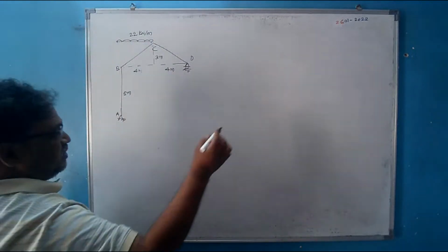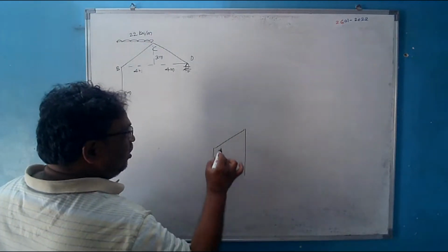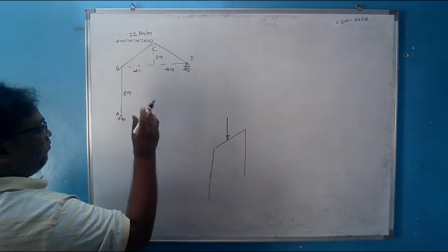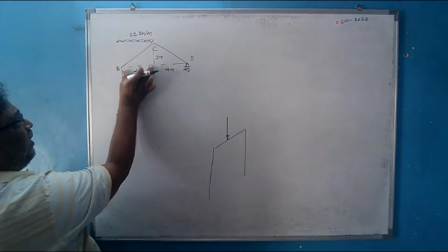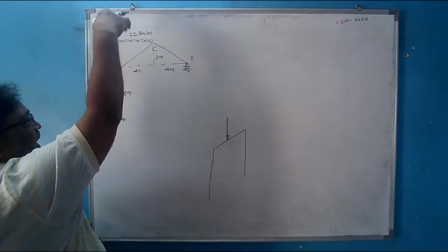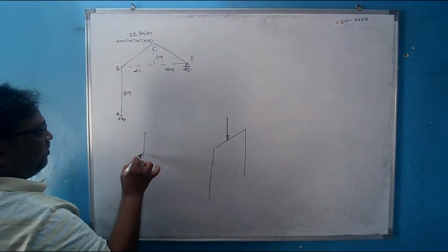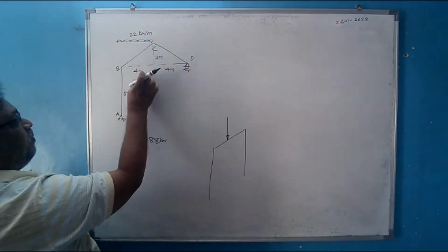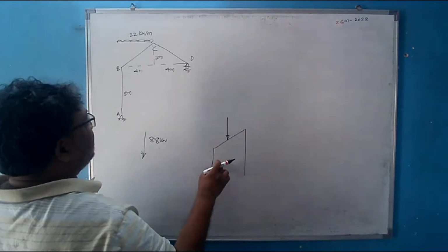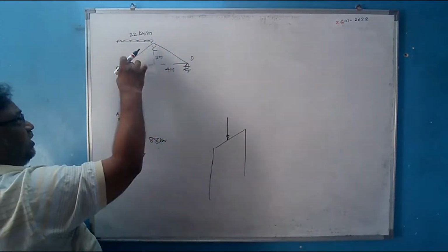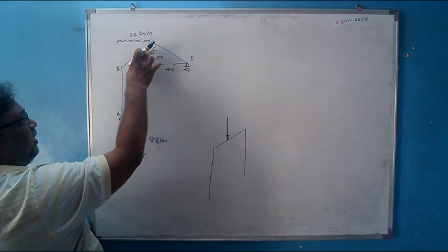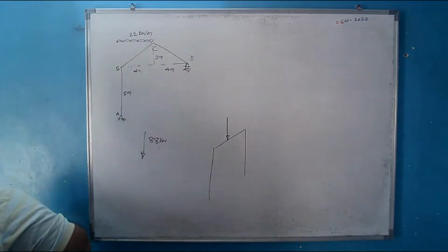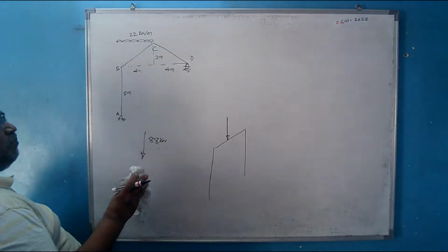It is acting vertical. जैसे हमारा जो पिछला प्रॉब्लम था जो हमने सॉल्व किया, तो उसमें भी यहाँ पर एक फोर्स ऐसे एक्ट हो रहा था. This was acting perpendicular to this member. So here also, if you will see this 22 multiplied by this span, because this force is shown vertically acting down, so it is acting on 4 meter span. So it means that actually it is an 88 kilonewton load which is acting down. 22 multiplied by 4. So here जैसे लोड पहले था अभी भी वही कंडीशन है. The force is acting inclined to the member. It is not acting perpendicular to the member. When the force is acting perpendicular to the member, it is much simple. When the force is acting inclined, तो हमको थोड़ा सा काम करना पड़ता है.